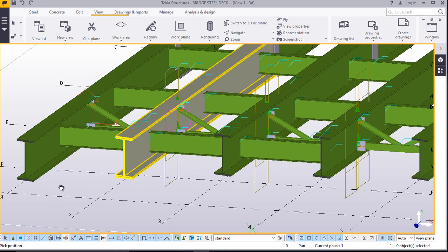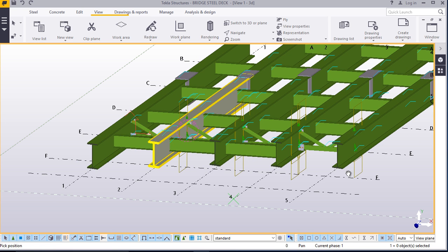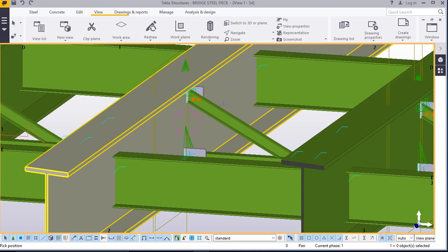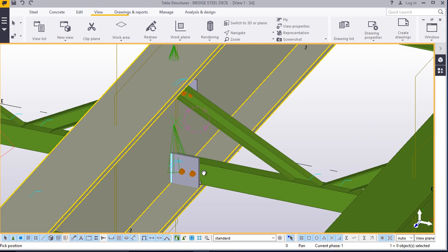Take into account that our beams, this is up with 55 millimeter, this up with 55 millimeter, this up with 110 millimeter, this down with 55 millimeter. So it's kind of a curve. Now if it started with this, they will not be the straight line. This should be slightly up, this should be slightly up, this should be the same level with this. Now we'll come here, click that and rotate.